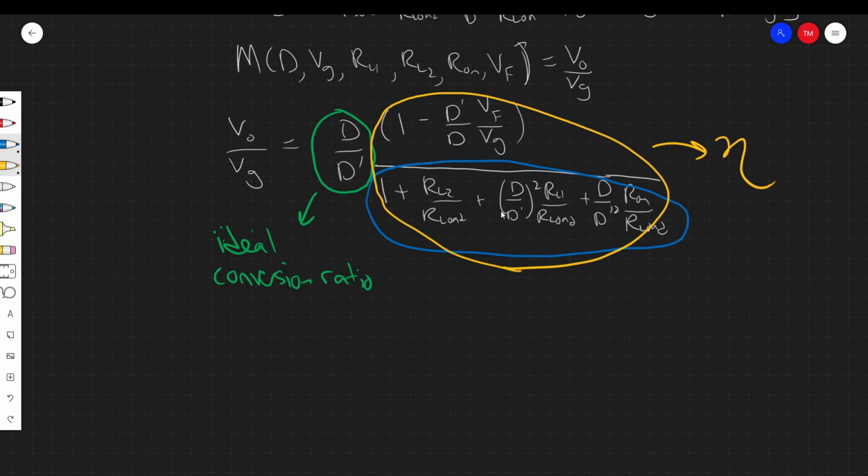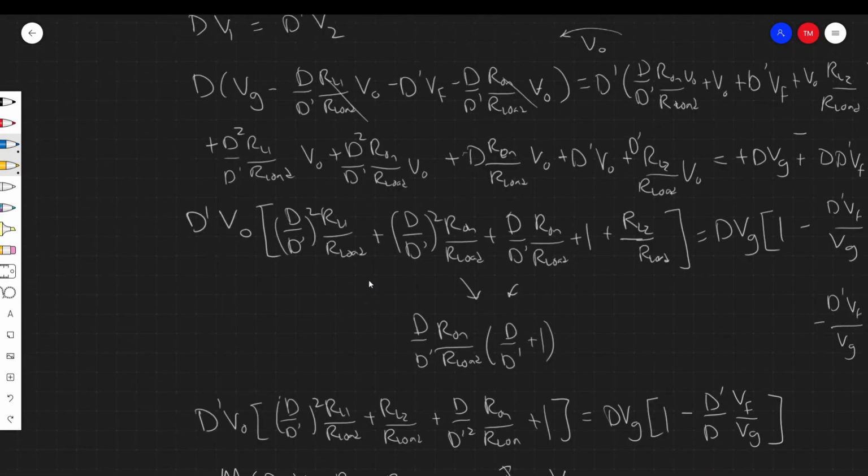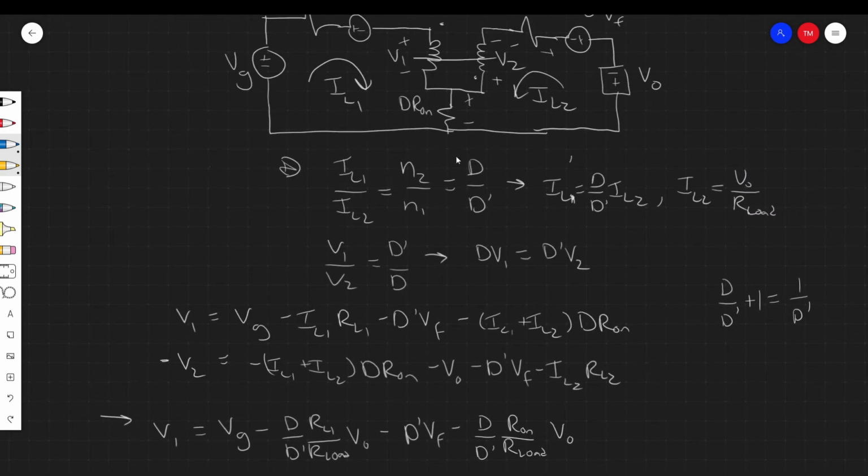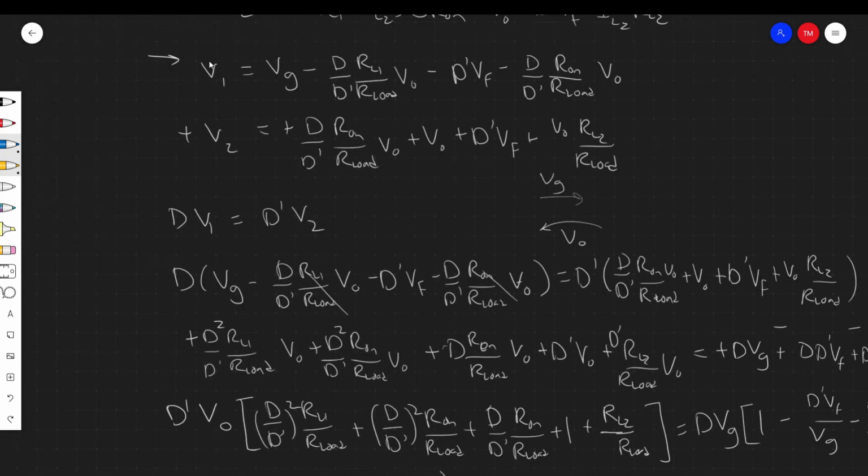So very complex converter, takes a lot of algebra to solve. You'll notice that a lot of DC modeling with losses takes a lot of algebra to solve. Figuring out this really important R-on coupling the two loops is really the trick to solving this converter, right? Solving this DC model overall. This is the trick, right? If you don't find this, then you're not going to get the right solution. That's what it's all about.